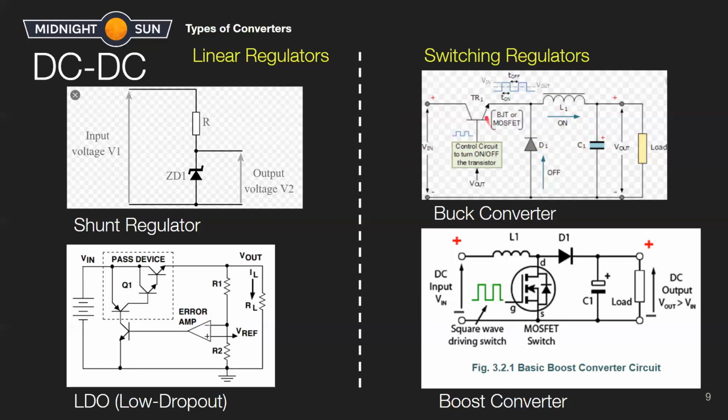It was charged during the on time of the transistor, so now it provides its own energy source and contributes to the load. And capacitors, unlike inductors, don't have an instantaneous voltage change, so the capacitor helps maintain that voltage we're seeing on the output of the load.